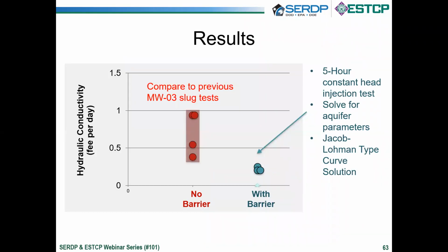After the injection and grouting process, we conducted a constant head injection test in the cells. And after solving for aquifer parameters, compared the hydraulic conductivities to previous slug test results.